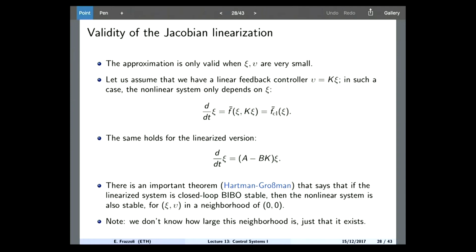Because what this theorem tells me is that, fine, I know that this system is nonlinear. I have absolutely no idea how to design a controller for a nonlinear system. However, I can take this nonlinear system, approximate it as a linear one, and use everything that we are learning in this class to design a controller for the linear approximation. And as long as I stay away from the imaginary axis and I keep my closed loop poles in the left half plane, lo and behold, by some magic, that control system designed for a linear approximation that does not exist will actually work on the real nonlinear system. You get the whole thing here?